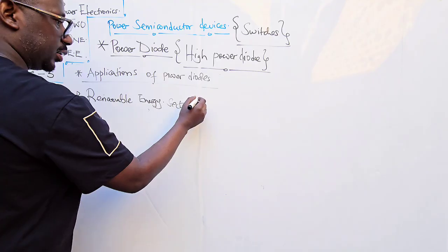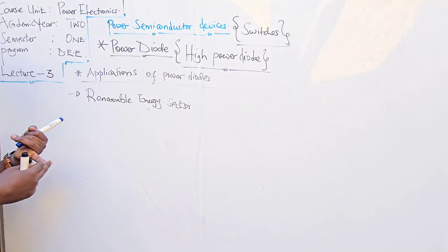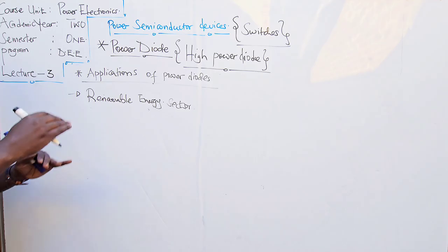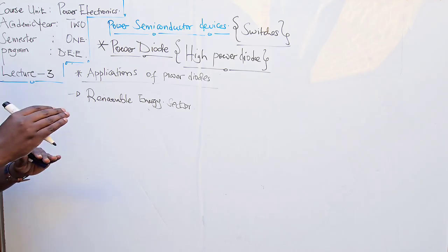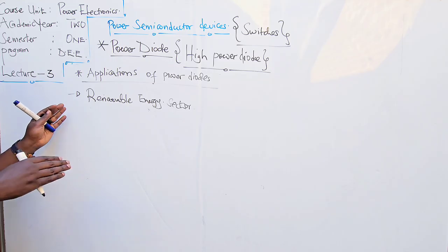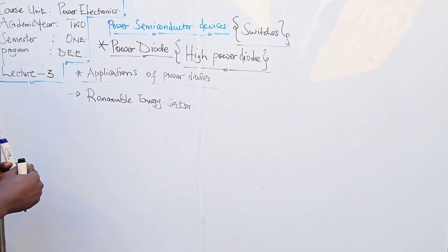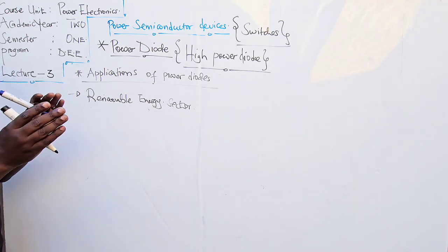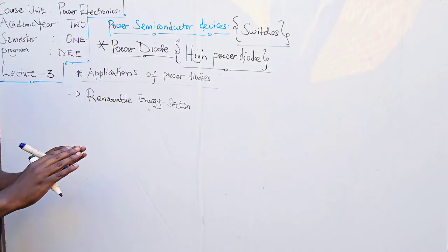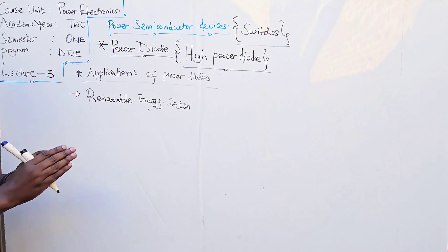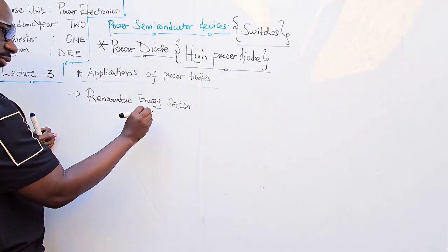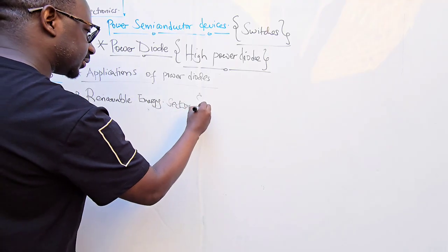So, let's say in converter circuits like buck boost converters, SEPIC converters, and other types of converters, resonant converters that do the charging, that convert solar panel voltages and currents to a voltage and current the batteries can safely charge, okay, and safely discharge. All right.